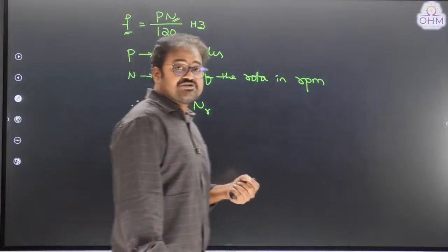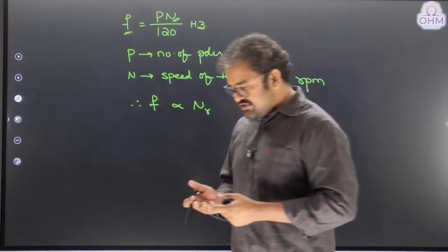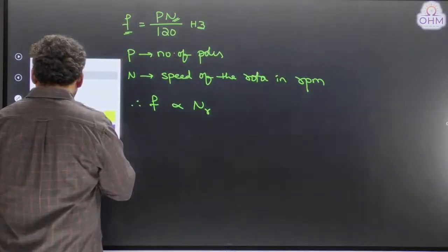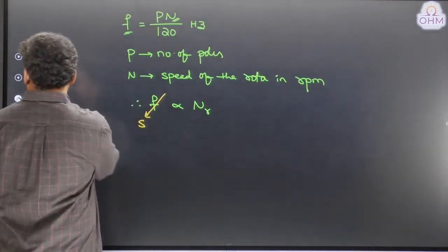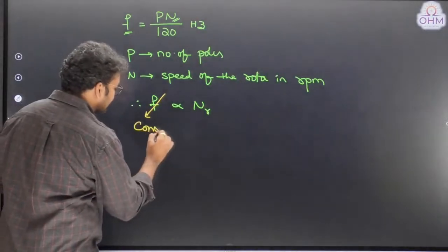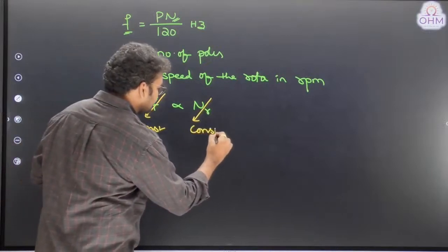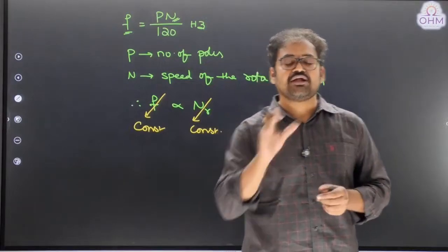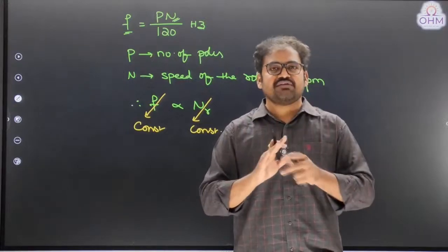In a power system, alternators are expected to generate voltage with constant frequency. Therefore, frequency can be constant only when the speed of the machine is constant. Yes, frequency will be constant only when we drive the rotor at a constant speed. Therefore, an alternator is a machine which has to be rotated at a constant speed always, ideally. But practically, speed will never be constant.